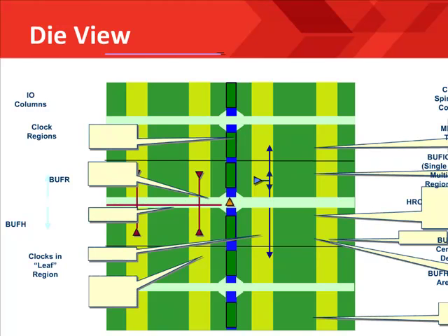Each device has 2, 3, or 4 I/O columns depending on the device density. This provides 1 or 2 columns of I/O pins per clock region. Note that the I/O pins associated with each column and a single region have their own I/O bank. Note that the MMCM tiles are associated with 2 clock regions, so ideally those MMCMs would be used to create